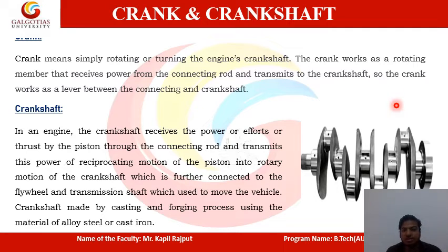Crankshaft. In an engine, the crankshaft receives the power or upward thrust from the pistons through the connecting rods, and transforms the reciprocating motion of the piston into rotary motion of the crankshaft, which is further connected to the flywheel and the transmission system shaft, which is used to move the vehicle. The crankshaft is made by the casting and forging process, using the material of alloy steel or cast iron. So this is the material.